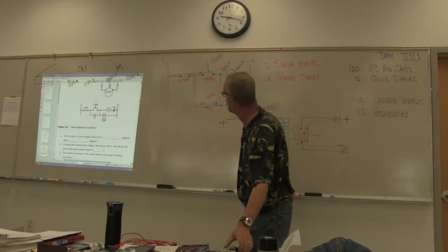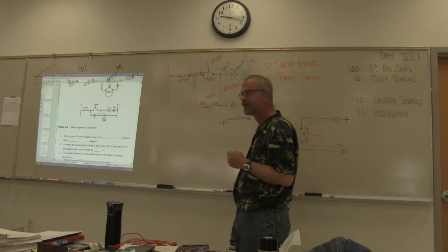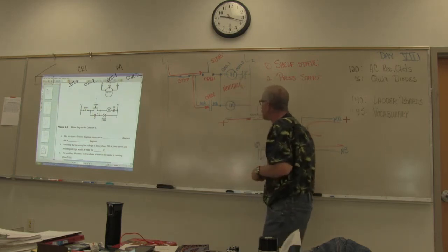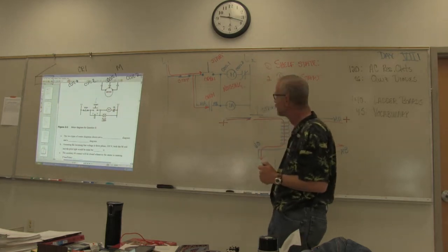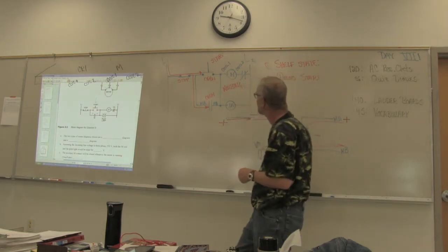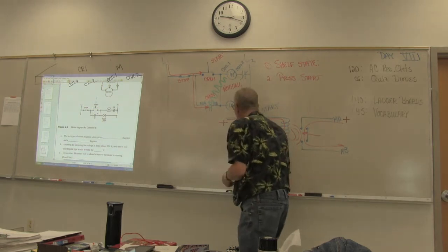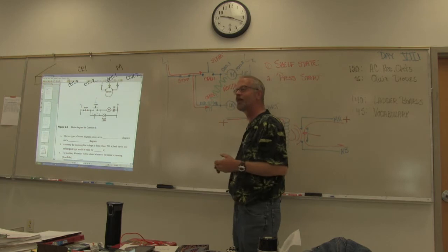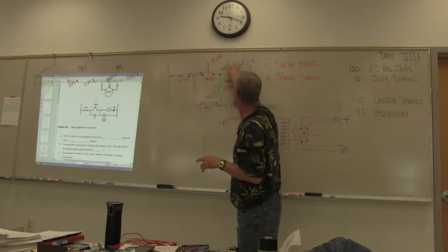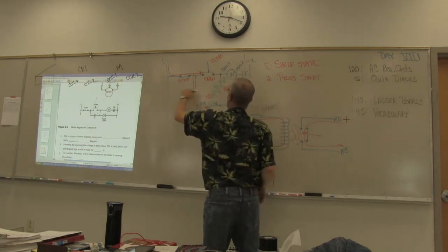I guess it's because the coil and the contactor don't look like they're connected that way. They're connected magnetically. I know, but because I'm used to schematics, the way it's drawn, it doesn't look like the coil is, you know, if they had the contactor under the coil, over where the lamp is, that would have made more sense to me. Yeah, but that's not the way it works. But that's what I wasn't getting, why doesn't the power trip the coil? Because they don't show this. Yeah, that's what I wasn't getting, the whole relay aspect of it. We don't want them in the same place because we want to make sure that when I'm controlling this in my little room, I'm not next to where all this is. So in the real world, I might have a big wall between these things.